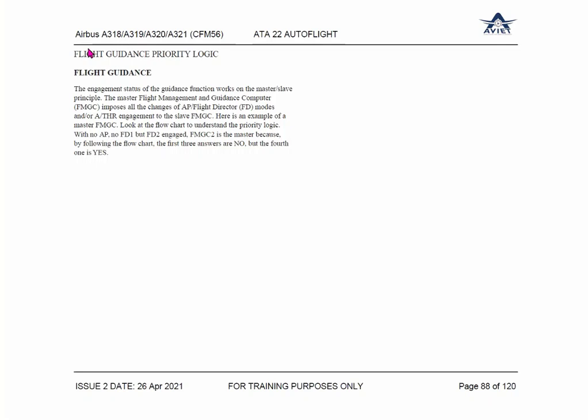Sir, if the autopilot 1 is selected, then FMGC 1 will be master. It will then be providing the flight director and auto thrust. In some other systems we studied, like landing gear complete retraction and extension, the LGCIU changes its priority depending on different ATAs.